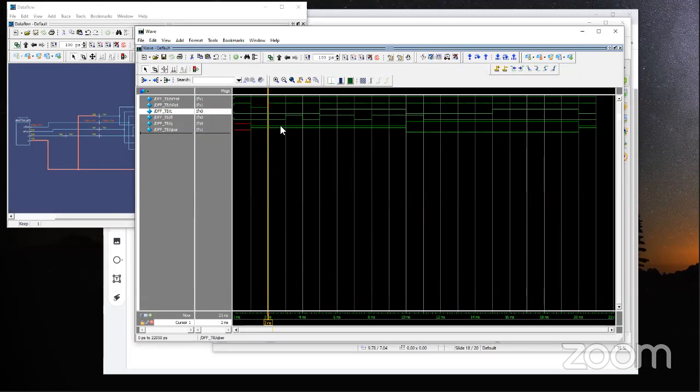Now let's follow the Q. During the positive edge, oh, actually this is a negative edge triggered flip-flop, right? So even on the positive edge, Q did not follow D at all. D was fluctuating, but Q is still stable at 0.